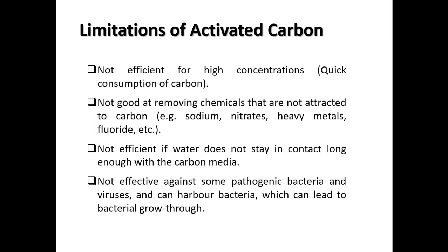And finally, it's not effective against some pathogens, like viruses or some kinds of bacteria also. In fact, it can be a site or a harbor for bacteria and microorganism growth, which will lead to side effects and more bacterial growth, which means more pollution to the water. So the carbon filters are sometimes considered harmful and they increase the bacterial growth in the water instead of reducing it. So these are some limitations of activated carbon.